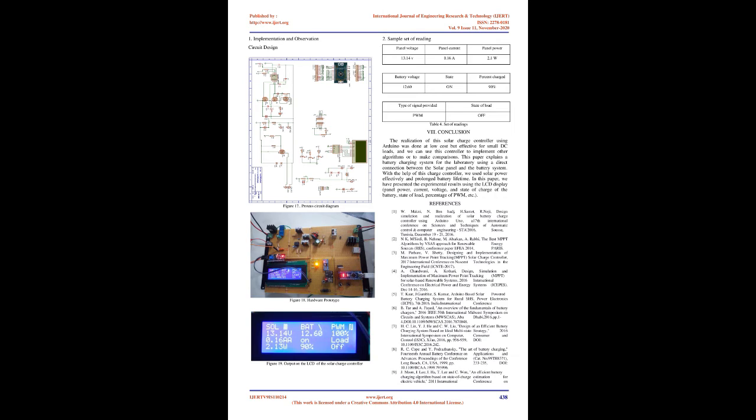Hardware specifications. 1. Arduino Nano. The Arduino Nano is a small, complete, and breadboard-friendly board based on the ATmega328, Arduino Nano 3.x. It has more or less the same functionality as the Arduino Duemilanove but in a different package. It lacks only a DC power jack and works with a mini-B USB cable instead of a standard one. Nano has 6 analog input pins and 14 digital I/O pins, of which 5 are dedicated PWM pins.